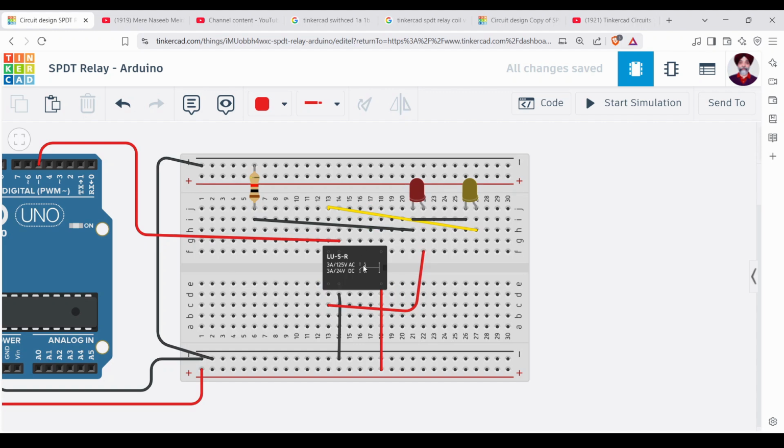And when this coil is switched on, that means power comes into the coil through terminal number 5 by giving the high on pin number 5. So now the normally open gets closed. So terminal 1 and 12 get connected to terminal number 6, which is actually connected through this yellow cable to the yellow LED, and the yellow LED should glow. Okay. So once we start the thing again, you can see it is alternating high and low, so alternating between the NC and NO, NC, NO, NC, NO, and so on and so forth.